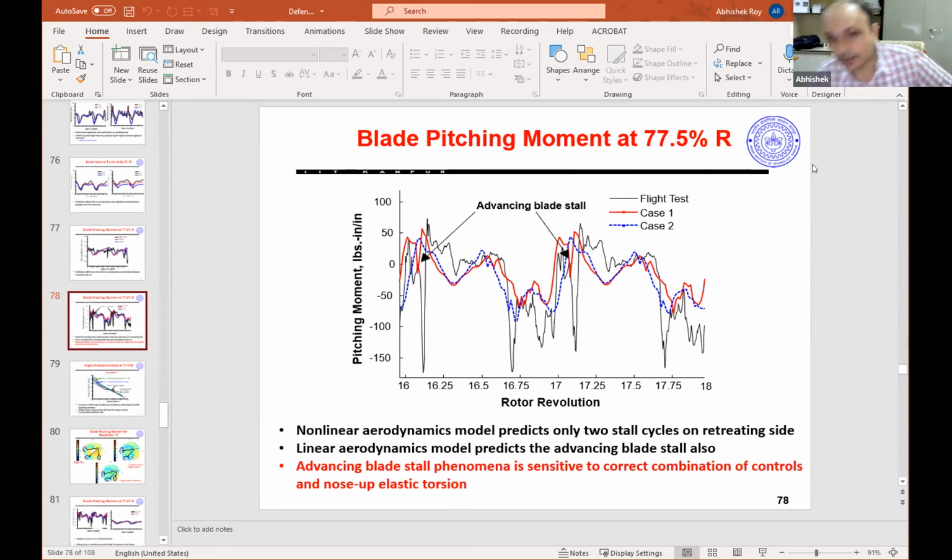These are all studied as part of unsteady aerodynamics: how this leading edge vortex is generated and how it actually travels. This whole thing is caused with a delay. Your stall is delayed because this vortex is traveling. The time it takes for the vortex to travel along the chord of the blade is a function of the frequency at which you are oscillating and other parameters also.